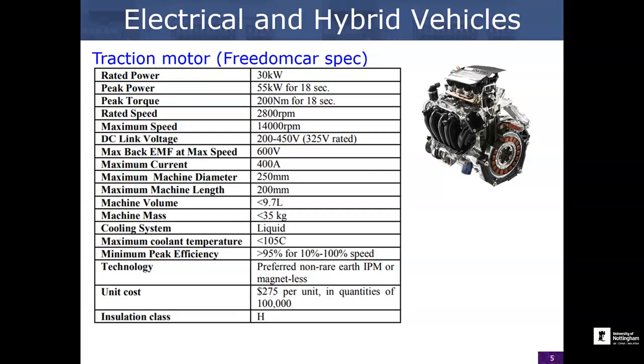It could be, as I said, anywhere before or after the gearbox. You have to operate at typical voltages within the low voltage range. So you can't have thousands and thousands of volts because it's impractical in a car type power system. You have to have some practical limits on current, and especially practical limits on things like sizing. So again, you have real physical limits where you can't make your machine enormous. You can't take up the whole engine compartment with a massive electrical machine. It's just not viable. So you have real limitations of how big a machine can be to do this job.